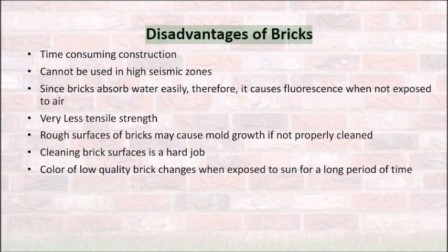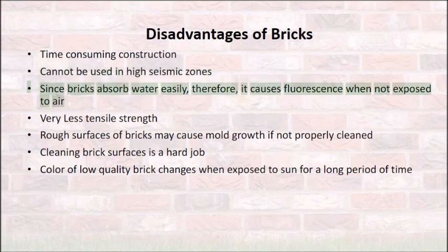Disadvantages of bricks. Time-consuming construction. Cannot be used in high seismic zones. Since bricks absorb water easily, it causes efflorescence when not exposed to air. Very less tensile strength.